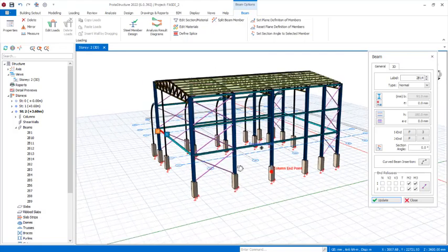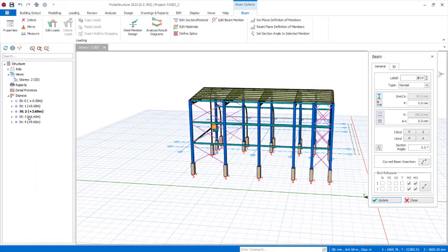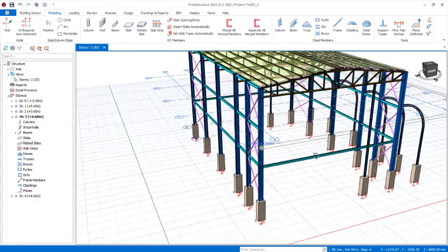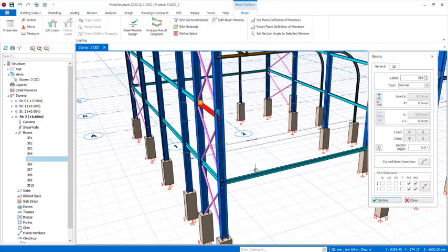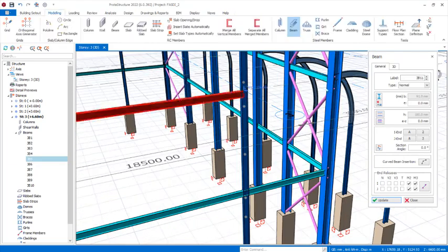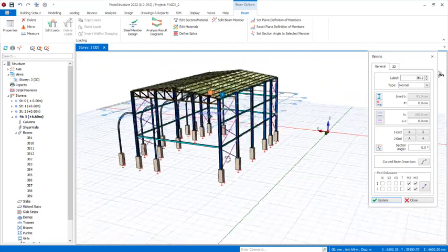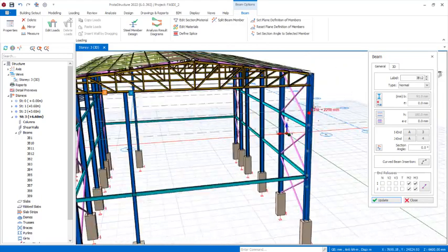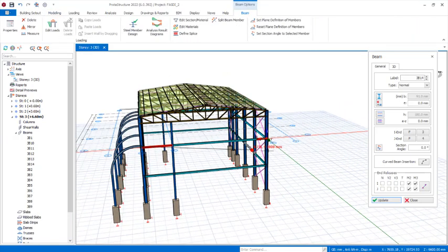So we will be moving the grid lines to the level story 3. So double click right there at story 3. You have this, so select this. We'll be using that property as well. At this point, you can pick this point right there, connect it here, and then place it just like this. Come over to this other side, and then you do the same thing. This point and here, just like this.